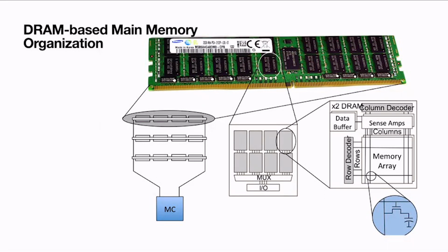In each device, we have sub-banks. That means a bank is divided into a set of smaller banks, which are called sub-banks. Let us say a bank is distributed across 4 devices, and each device holds 1/4 of that bank. There are several such sub-banks inside a device, and each sub-bank consists of a set of DRAM memory arrays. This particular example is an X2 device, in which 2 DRAM arrays are placed. It can also be X4, 8, or 16, and so on.